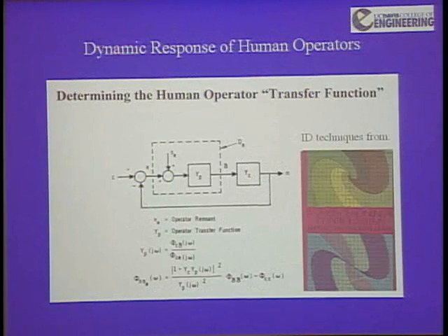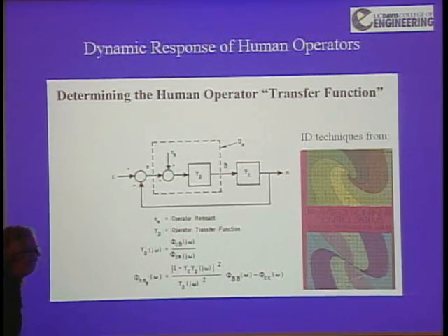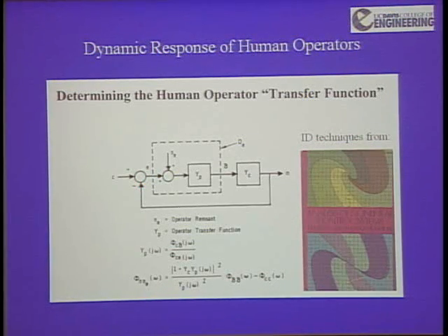Okay. How do you make these measurements? Well, it's quite simple. Again, here's McRuer's name appearing, Dunstan Graham and Duane McRuer. It's a very fine textbook called Analysis of Nonlinear Control Systems, first published by Princeton University Press. Here's a task. We've got a controlled element. We've got a pilot. I can measure the pilot's transfer function as a ratio of cross-power spectral densities. Take the cross-power spectral density between input C and the operator's output delta, divided by the cross-power spectral density between error and the input. That gives me an estimate of YP.